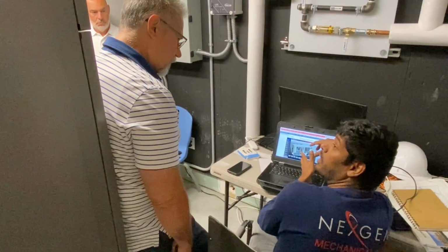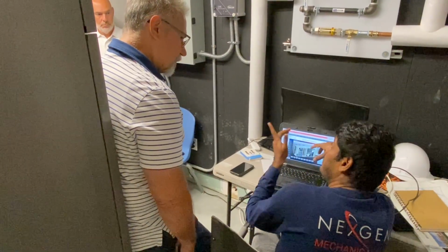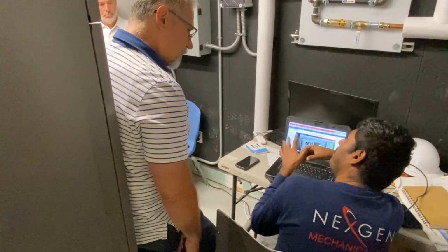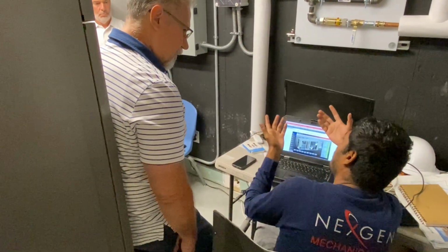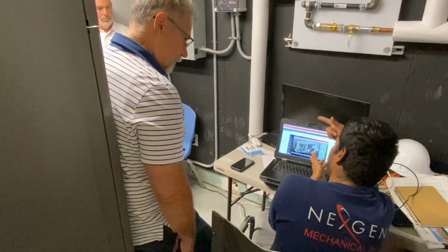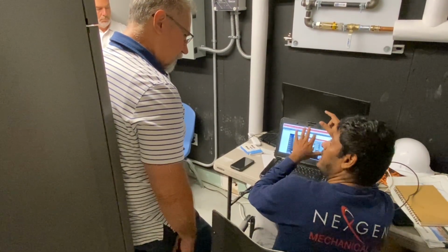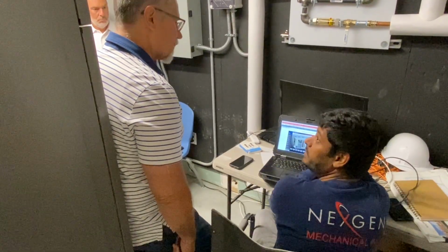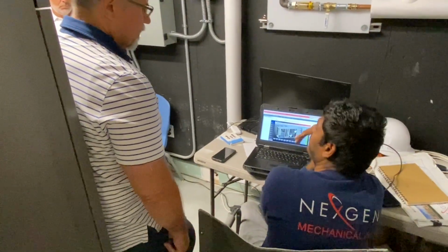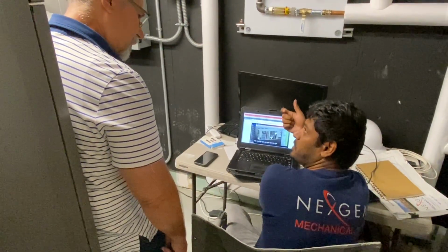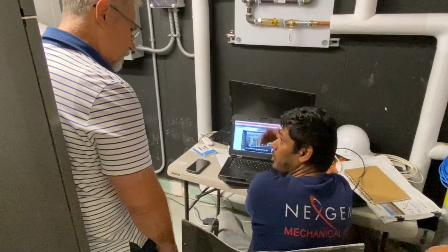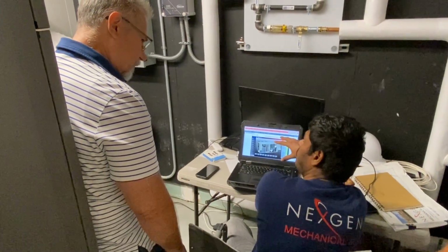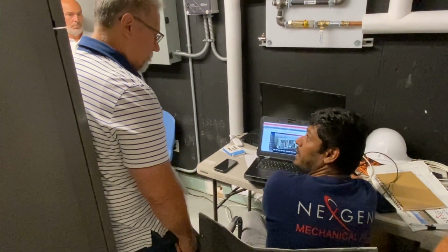I'm going to have a CO2 control on my unit. The VAV is going to have a local CO2 control by opening the damper. That command is going to be passed to the RTU, and it's going to start taking control of the CO2 as well, bringing in more fresh air. And again, that 10% is still adjustable. You can make it 20%, or even if one VAV is trying to meet a CO2 demand, then it will open the damper.